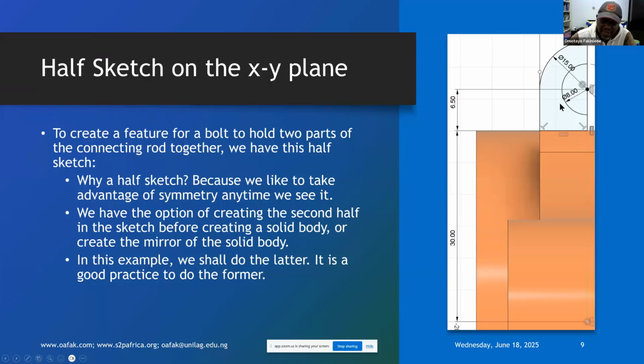So here you use this profile, just by extruding on a profile like this. This profile is easy to make. You start with a 15 diameter circle at point 36.5 here. Once you make this tangent to it, you take off bodies that you don't need, and you do another circle of radius 8 here. By extruding and mirroring, you'll be able to get what we have next.